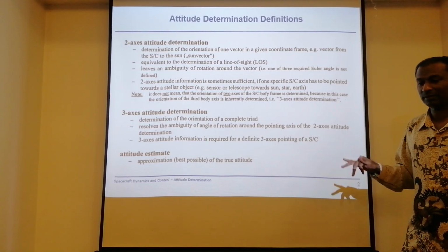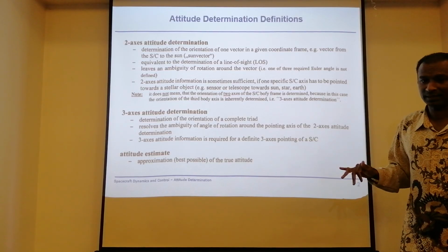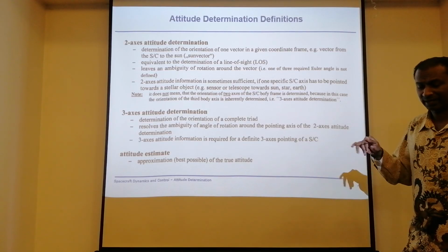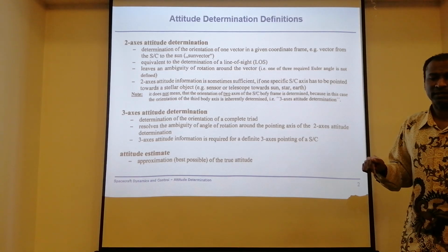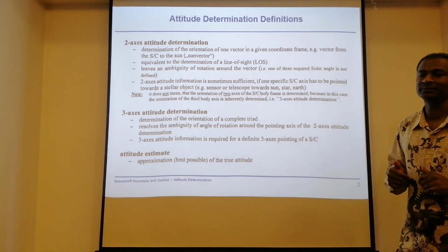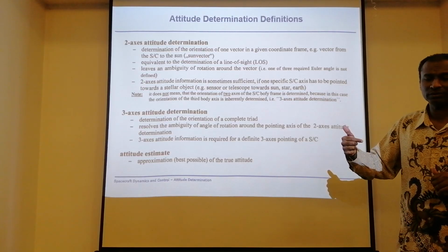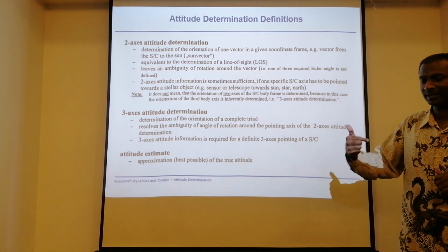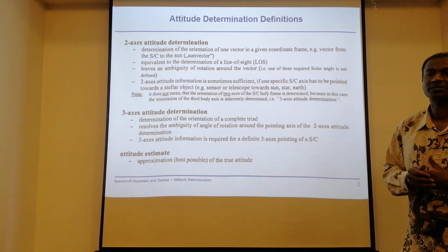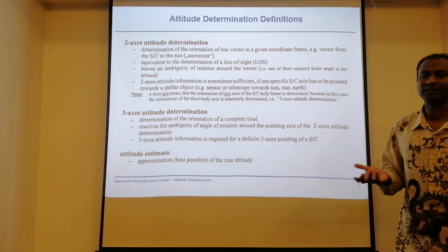I assume that both of them are coupled in any case. So I can have that motion detected via my sun sensor, and for the z-axis, which is the yaw rotation, I can simply have a gyro to give me that motion.